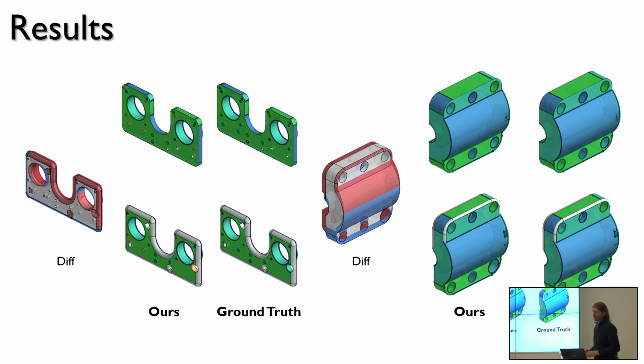And I want to point out that if we could have matched something that we didn't, we've just gotten back to the base condition if someone has to match something manually if it's used in a reference. So that's no harm, no foul. That's an okay situation to be in. The situation we really don't want to be in is making an incorrect match between two BREPs, because then an erroneous reference can be made that will be a silent error to the user.